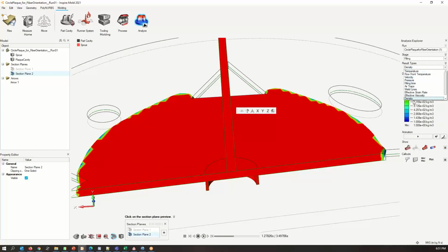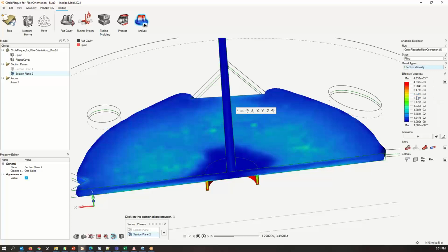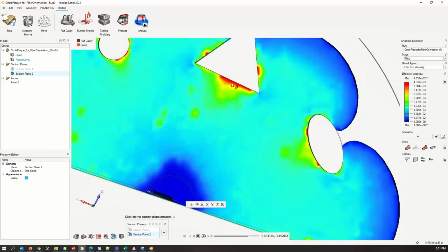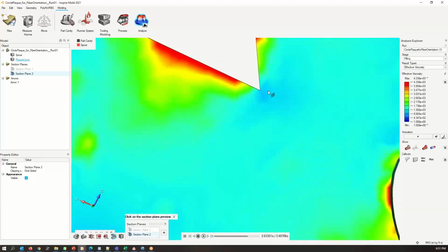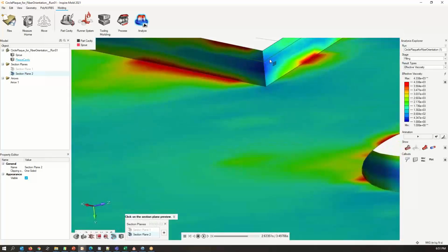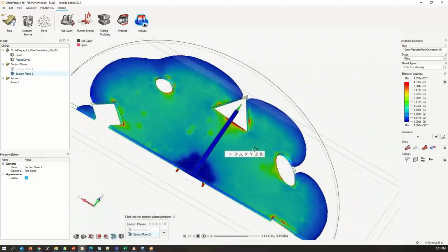All right. But we can look at our viscosity as we go, right? Just like I was looking at before. And I can say, hey, right as this stopped, viscosity gets higher, and then it's being made to flow around that. Viscosity drops right near those corners. It's going to drop as it comes around the outside of this. This being rounded, it's not as dramatic. Here, it's much sharper, and so I see this band right here that's causing that viscosity to drop. And especially as I look at it through the thickness, it drops tremendously right in here. That's going to add to flow near that corner,